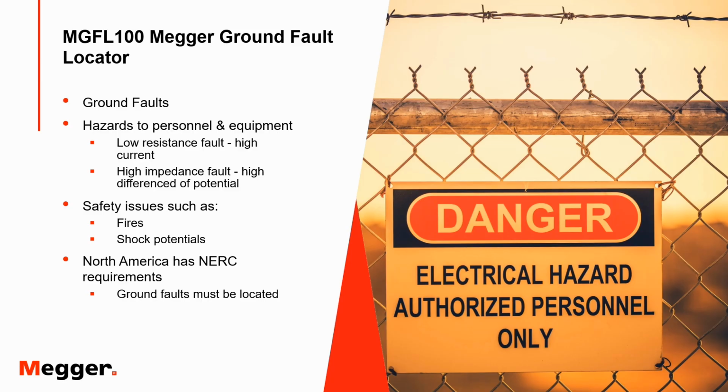A low resistance fault can lead to high current flows that can cause equipment to trip offline or even fail. A high impedance fault can lead to high differences of potential, leading to shock hazards. Ground faults have led to safety issues such as fires as well as shocking of personnel.